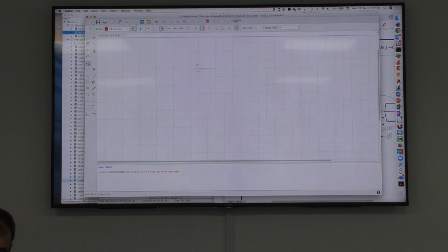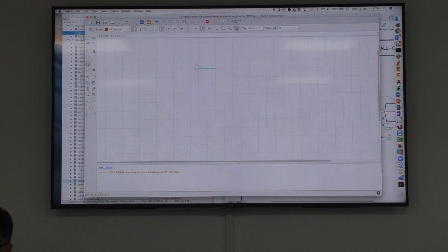If you have our LM555, I have a GND pin, then I want to see that's GND or it's V+, or I also want to see it's assigned to pad 5 or 7, so that makes the schematic more informative. So I think it makes sense to decide here. In our symbol now, I decide both. You see, it's both names, the pin name and the pad name, or the visibility of, that's the other option. Of course, you can change this all afterwards, after I've placed the pin, but it makes sense to do it in the beginning, so you don't have to click again.